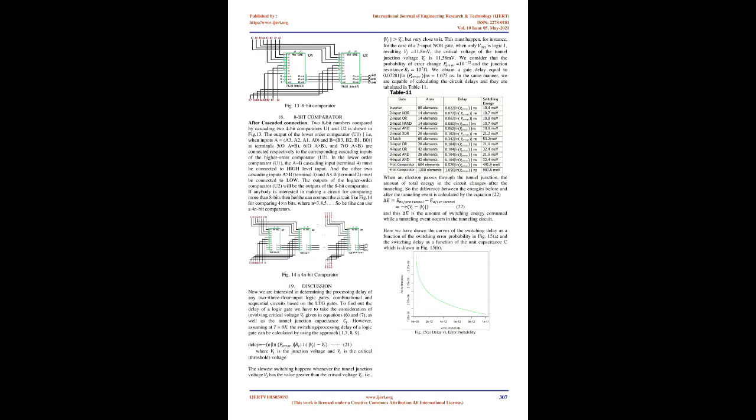From table 9, we observe that when the comparing input data A and B are equal, the outputs in the red color box are not acceptable, because at the same time 2 or 3 output levels can be high or 2 or 3 output levels can be low. For a comparator, only one output level will be high and the other 2 will be low.